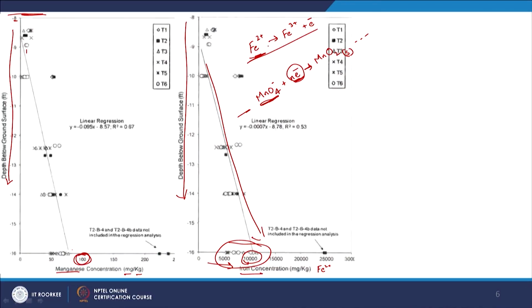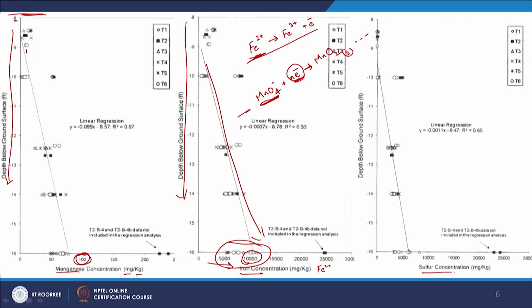So, you will have a redox reaction out there, and this Fe2+ will reduce MnO4-, or you can even say MnO4- will oxidize Fe2+. The net effect is that some of the MnO4- or permanganate that you are going to put into the soil is not going to target the relevant contaminants, but is going to be consumed by the ferrous iron, which is at considerable concentration in the relevant soil. So, that obviously needs to be taken into account.